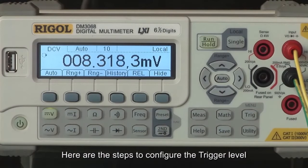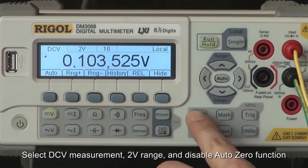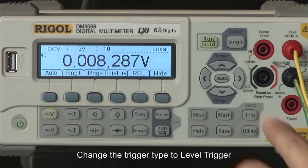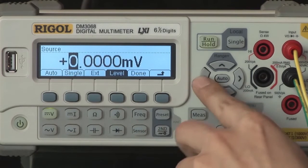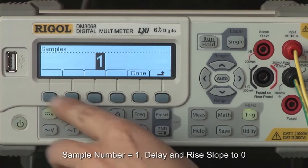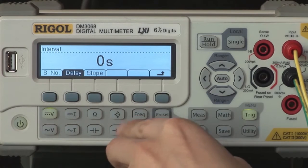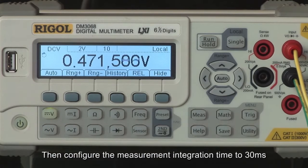Here are the steps to configure the trigger level. Select DC volts measurement, 2-volt range, and disable the auto zero function. Change the trigger type to level trigger, and set the level to 500 millivolts. Now enable the trigger function, and then configure the trigger parameters. Sample number to 1, delay and rise slope to 0. Then configure the measurement integration time to 30 milliseconds.